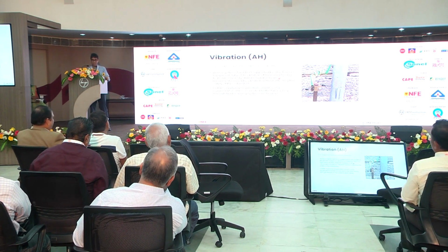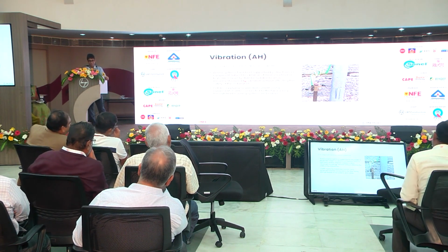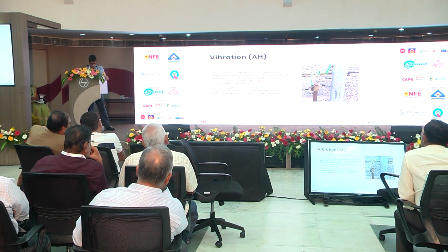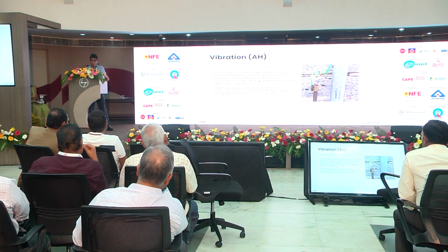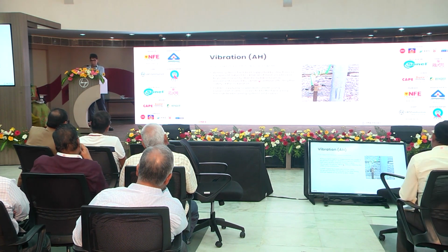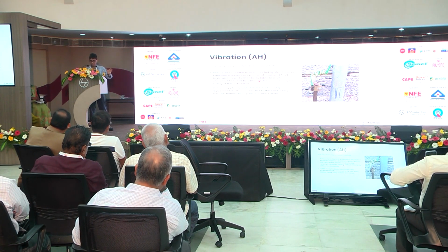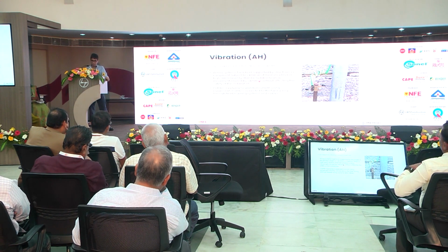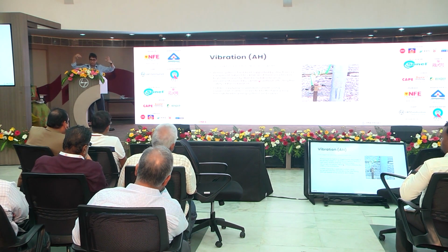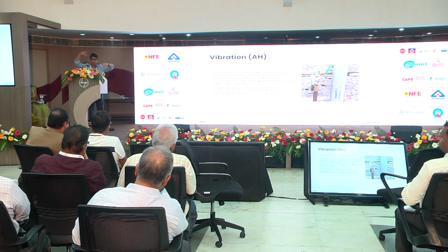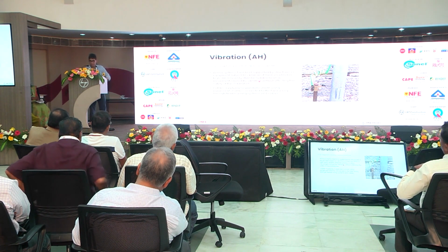And especially for medium or severe or high vibrations, this must be considered. And if you remember from yesterday, must be considered means you have to do it or you have to find another equivalent protective measure that gives the same degree of safety. Now, flexible cables may need to be used in applications like this, and only in applications like this, because let's say you have a suspended luminaire, a hanging light, you cannot use a rigid cable. That thing is not going to be able to withstand the movement due to the air.